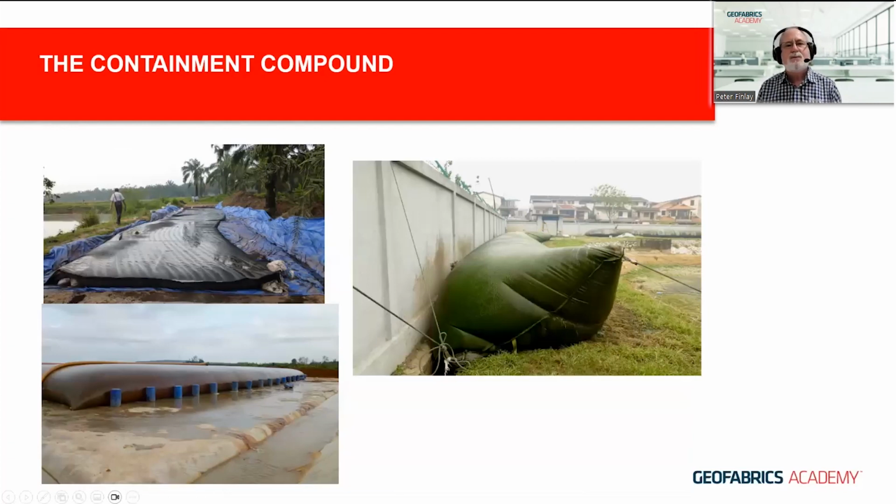So as I've said, if you put geotube on a sloping surface across the width of it, you will get them rolling, or you will get them sliding and getting a banana effect. And if you fill that any more, it's probably going to end up rolling down into the pond.